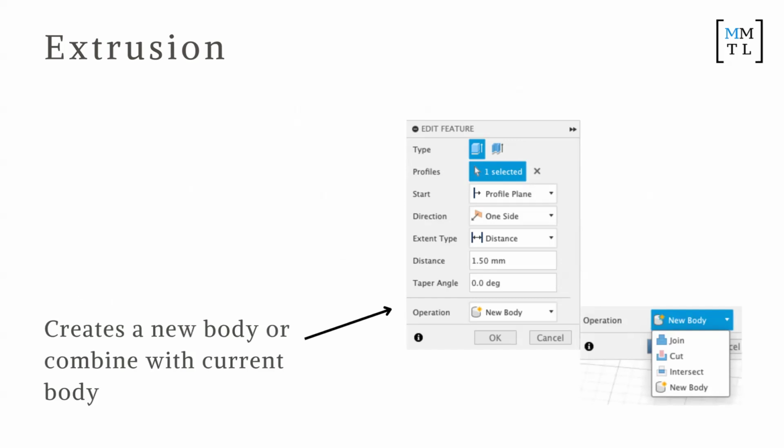Then you also see something called components, which are basically folders for bodies. When you're doing a complex design, split it into logical or natural folders, and then keep your bodies in the right components. That's a critical thing, particularly for more complex designs.